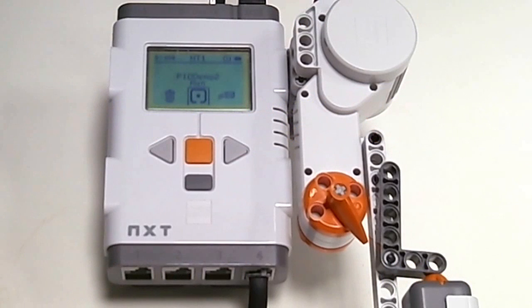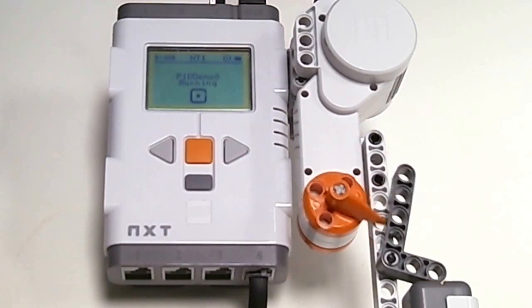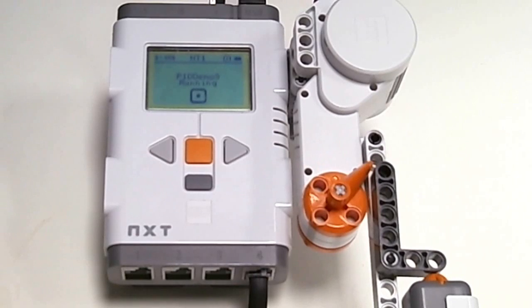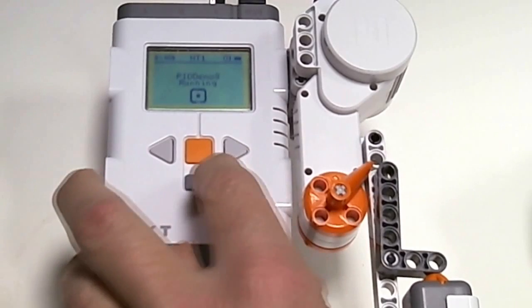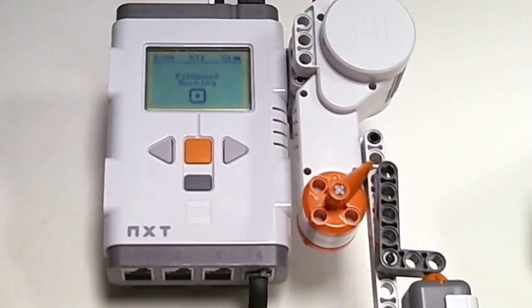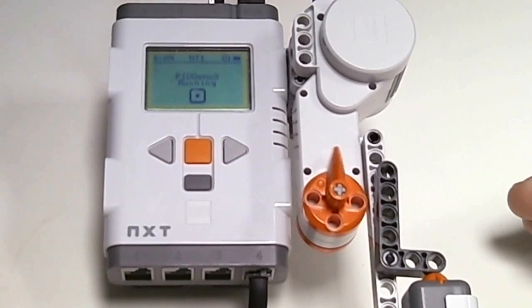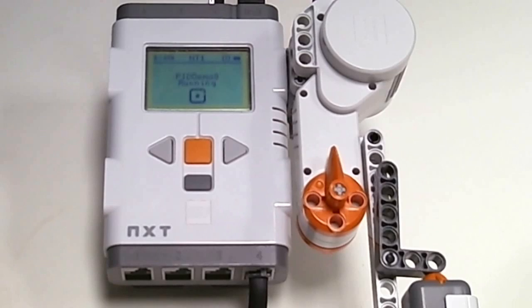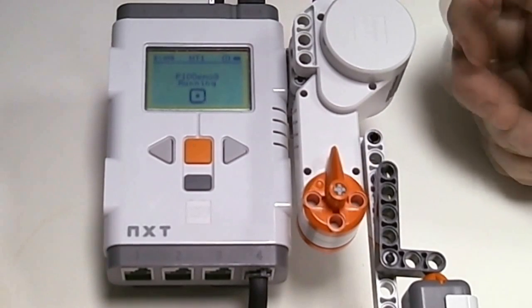Let's go ahead and download this. So you saw it pressed the button and it actually went all the way past until it released it. And then if I start somewhere else, it will still do the exact same thing. Now in this demonstration, I'm just using angles like minus 45, 0, 45, and you can use any angles. You can say 1,000 degrees, 10,000 degrees, whatever, positive or negative, and it will go to that location. It will spin as many times as it has to get there.